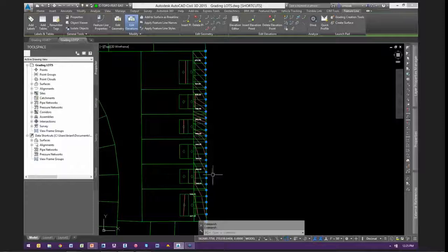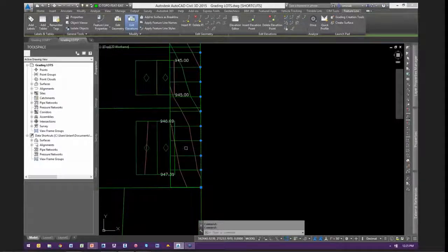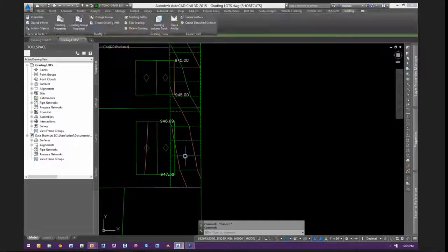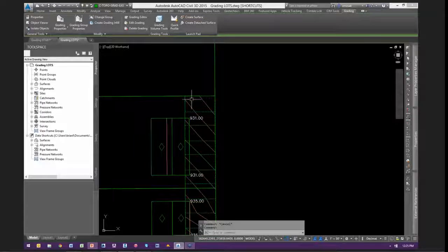So I can drop a feature line there, and then from right-of-way, again, we want to assign pad elevations, some kind of typical or constant slope up from right-of-way. So what I've done is I've taken that feature line and attached a very simple grading object to it. If I go through the editing of this grading option, you can see it's at a 5% grade coming up at a 5%.